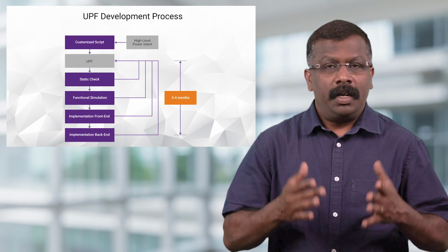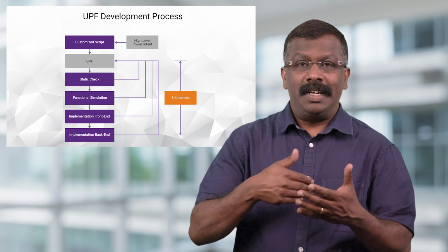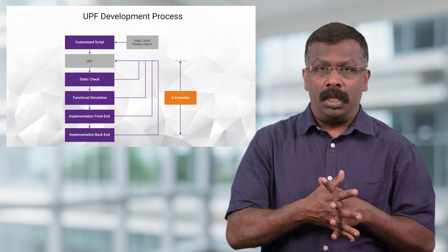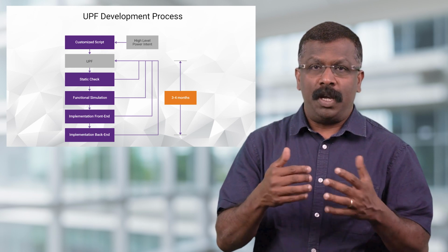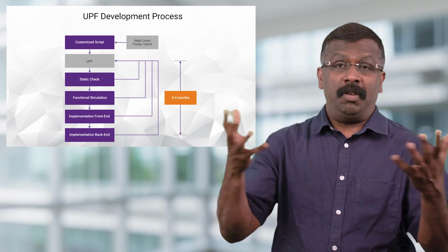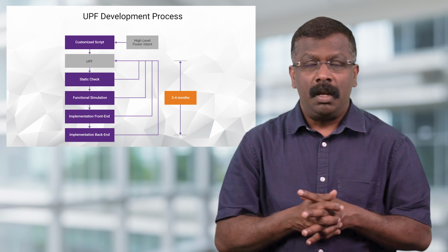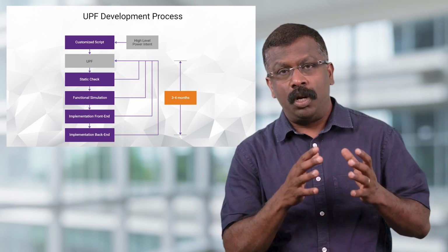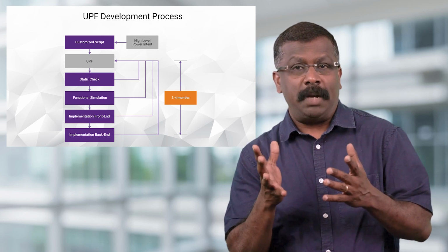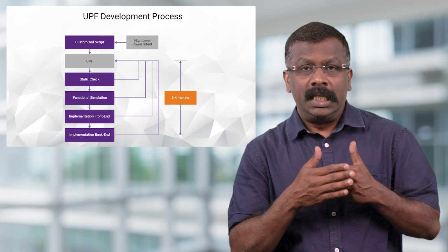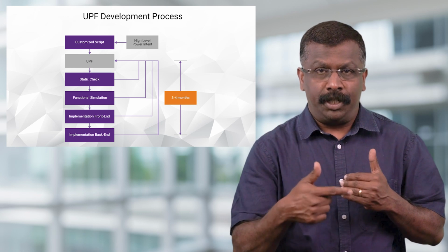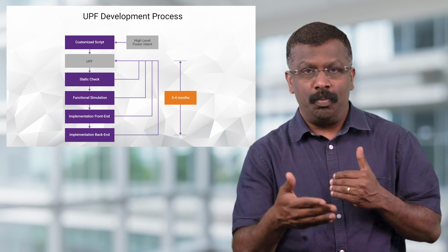Typical UPF development process in any chip design houses involves using custom developed utilities to generate complex UPF from a high level specification, which could be from a Microsoft Word document. These customized utilities focus more on language, syntax, and semantics, and lack the understanding of the tools in the flow. This leads to many iterations across the flow to get a common UPF.